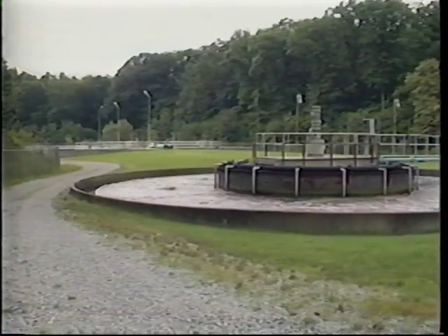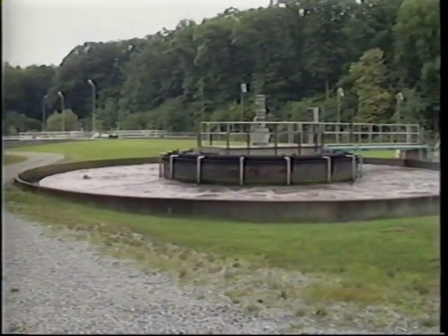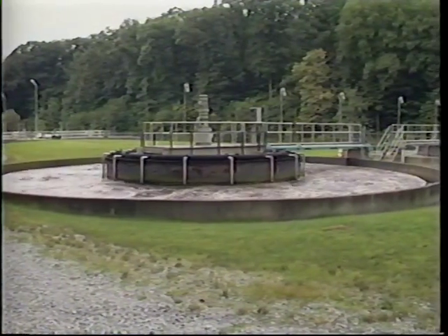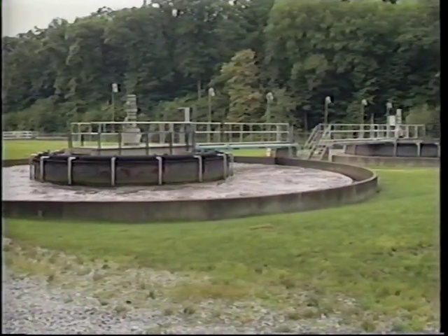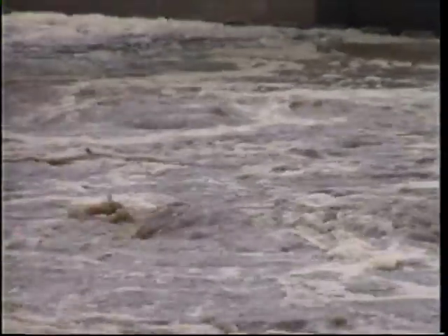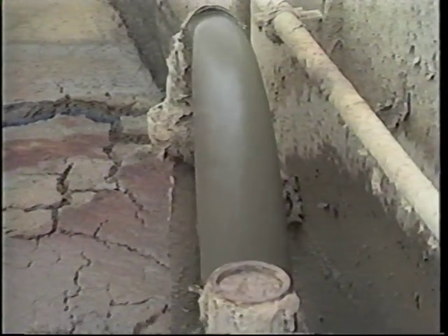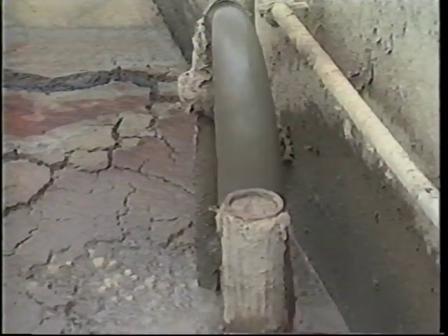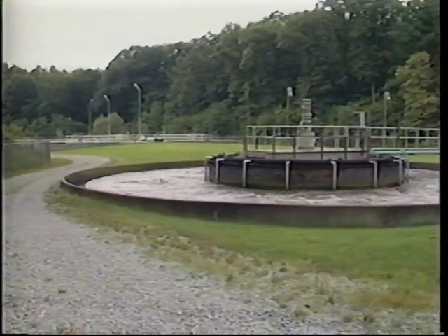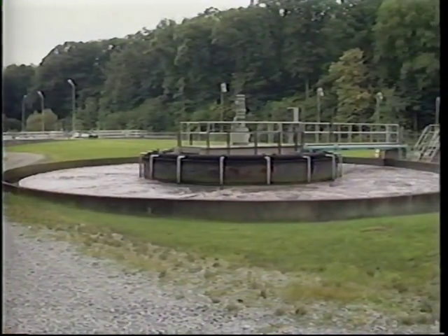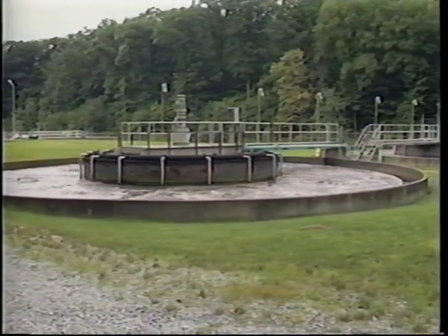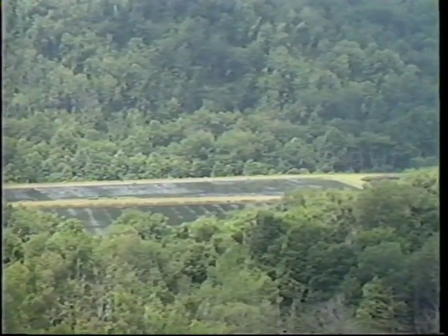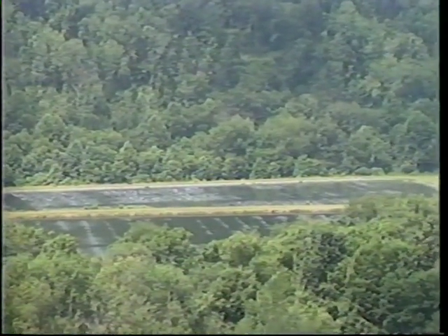Now, let's take a moment and quickly review the activated sludge and lagoon treatment systems. Both treatment systems utilize carefully controlled microorganisms to consume the pollutants in the wastewater. Both systems produce excess biosolids or sludges that must be removed, treated, and properly disposed. Activated sludge systems are more compact and require a lot of operator attention, while lagoon systems require large amounts of land and are not quite as process control intensive.